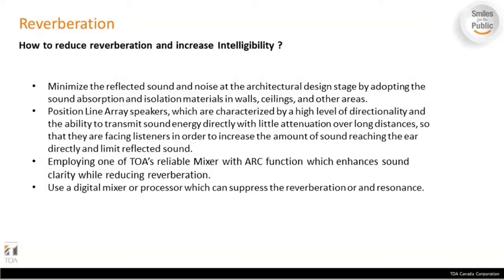Also, we have to be careful, if it's a huge setup like a gymnasium, an arena, a theater or an auditorium, in how you position the line speakers, which are characterized by a high level of directionality. We have line speakers which you can suspend at a particular height.